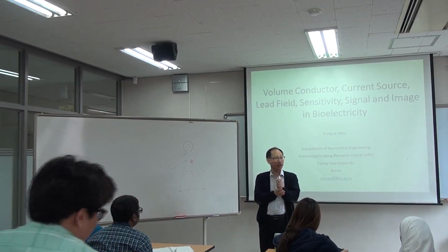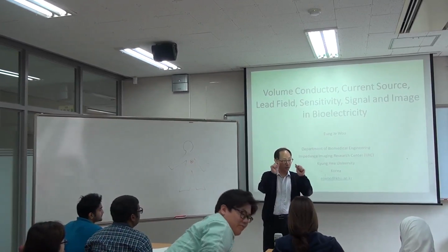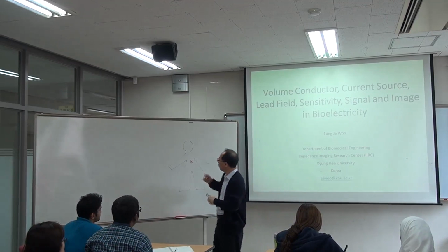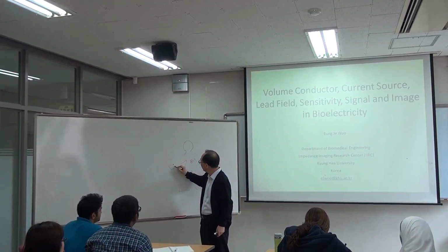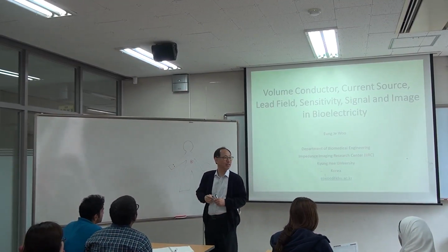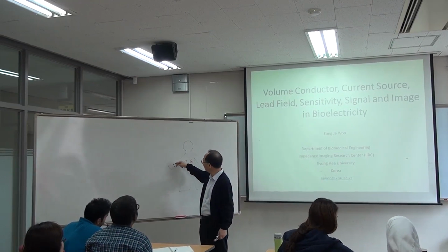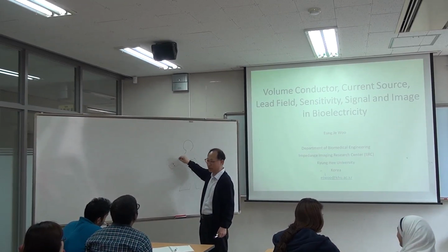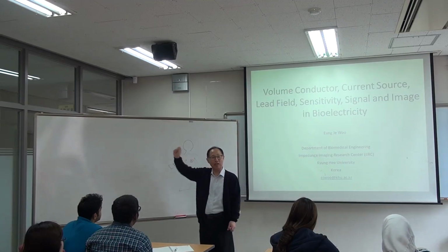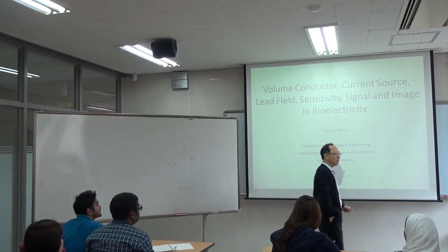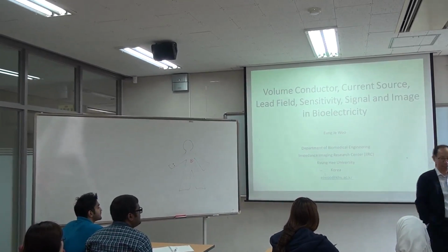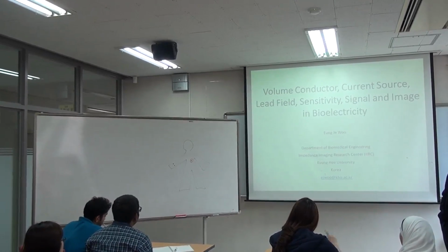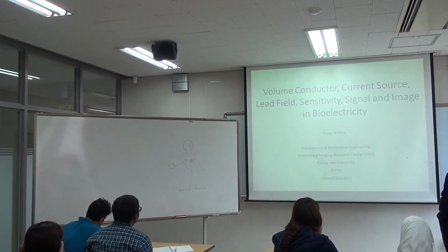To measure electrocardiogram, you have to measure the voltage difference between 2 points. So you have to have at least 2 electrodes, right? So he installed 2 electrodes like this, under the watch. And inside the watch, there's going to be a lead wire, an ECG amplifier, and an A to D converter, and he's trying to display the ECG signal and detect heart rate and so on. So what's the problem here? Do you think he's going to be able to detect ECG or not?